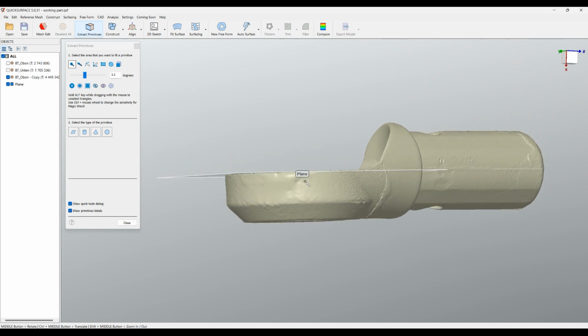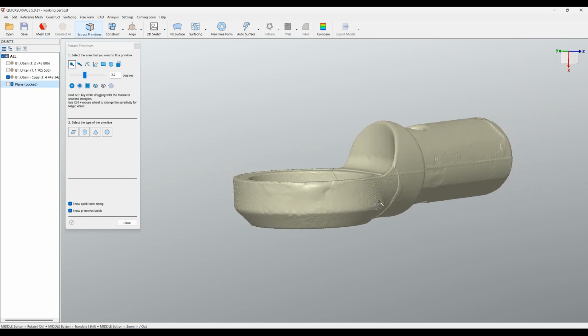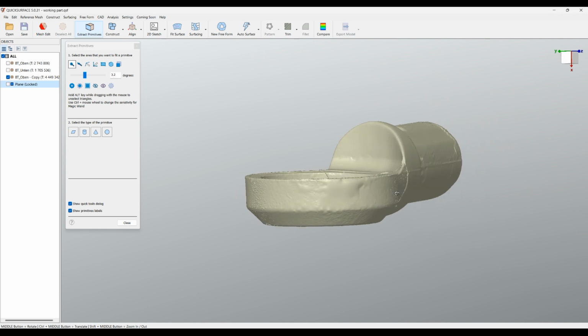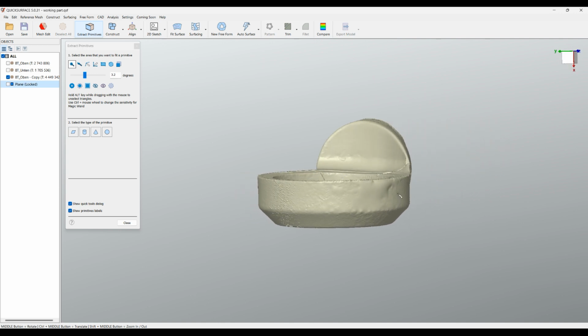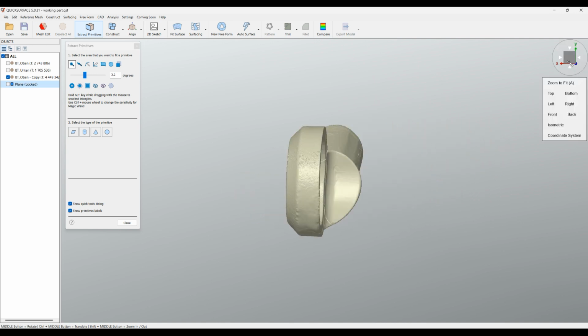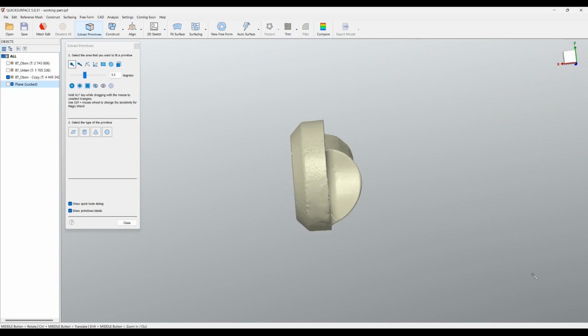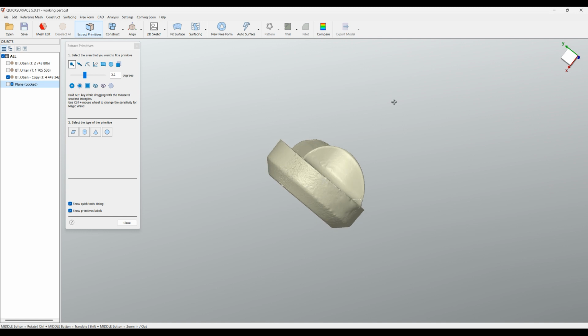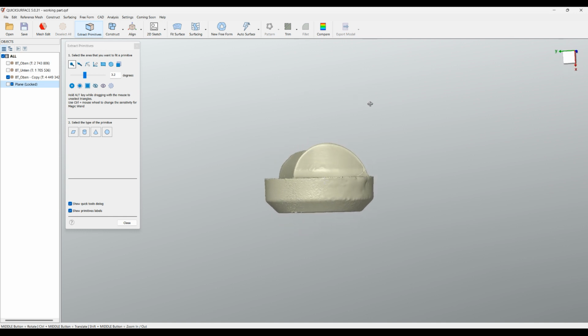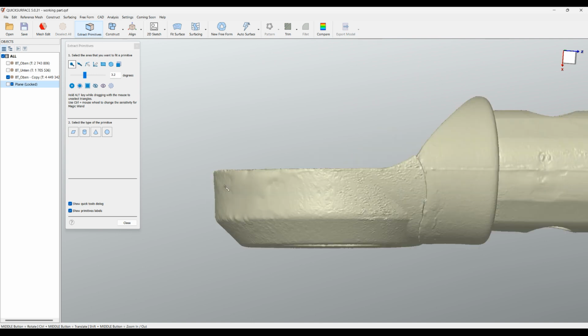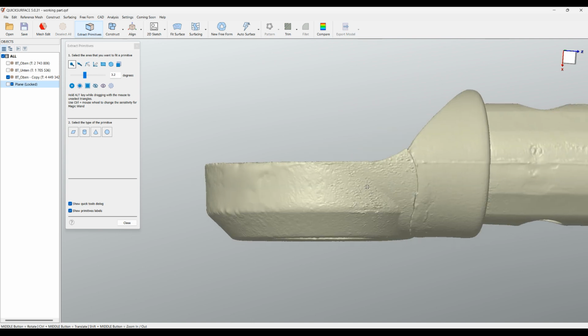Now I need to create my outer cylinder. I can probably hide this plane. I'm trying to get the selected area here through which I'm going to generate my cylinder. I'll place it in a standard view, something like this one. I can hold the Alt key so I can rotate around the view Z axis, and I can use the arrow keys to rotate by 90 degrees.